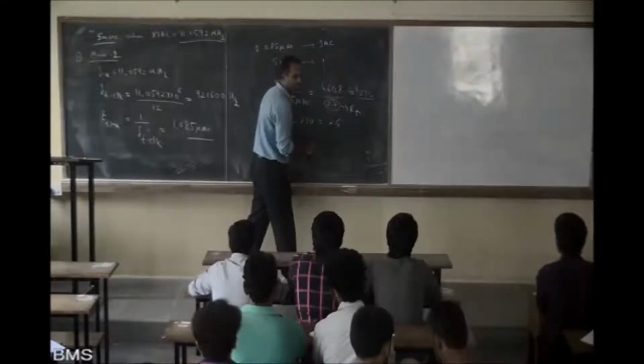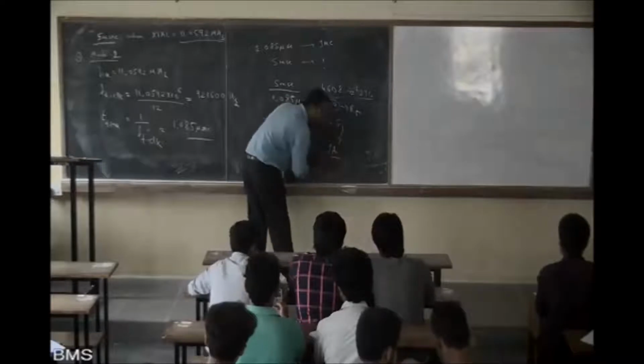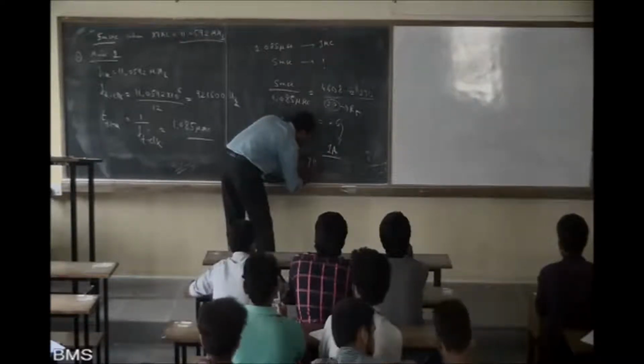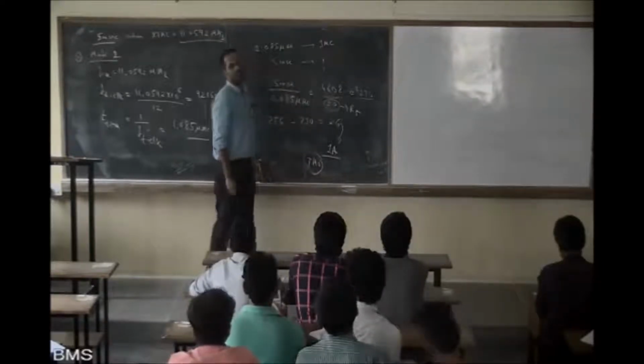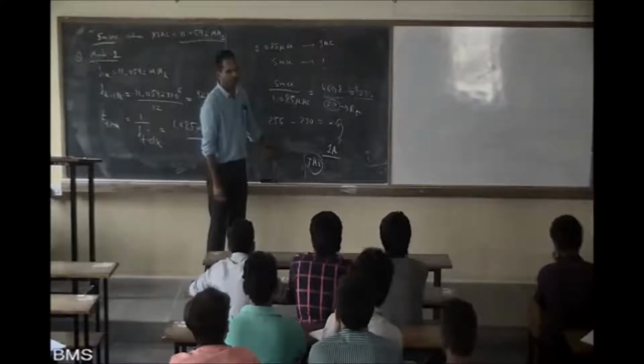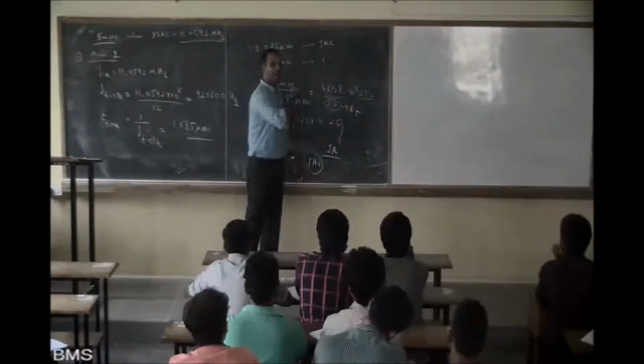Hexadecimal value of 26 is 1A. 1A is the value which will be stored in TH0, which will be copied to TL0.